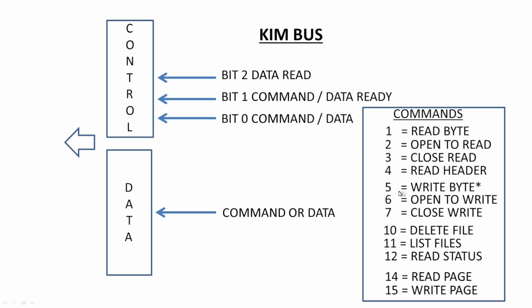But there's this sort of write byte command. There isn't really a write byte command, because the way data gets transferred backwards and forwards, one side knows that there's data coming in here, so there isn't a command saying write byte, you just put a data byte out, because the solid state drive will be ready for it anyhow.